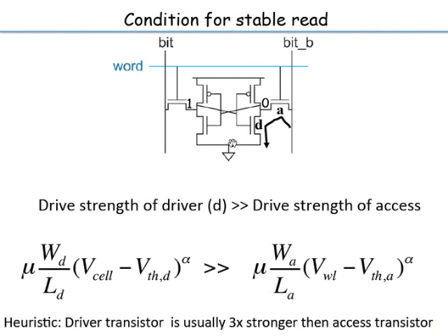When you put fewer cells in the column, for each column you have this circuitry to sense, to write and so on. So you are increasing that, because every time you partition the memory, you start off with a monolithic memory array, say a million bits in a single rectangular or square array, 1000 by 1000 cells. Now you have only the circuitry in the periphery of the array: decoders to decode and select, and then the circuitry in the column.